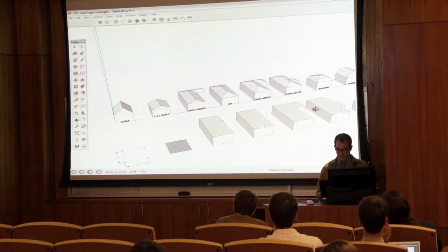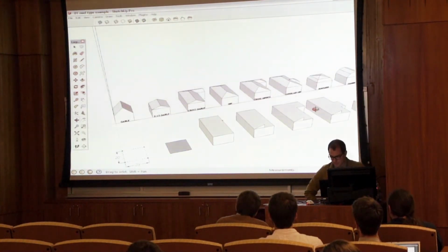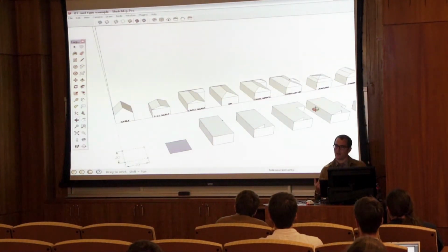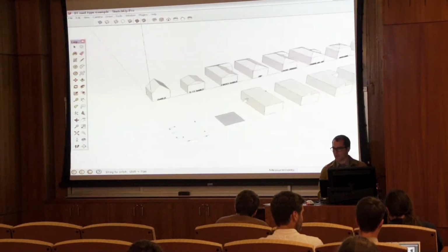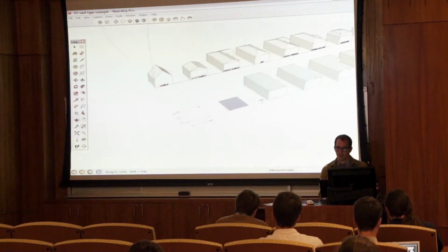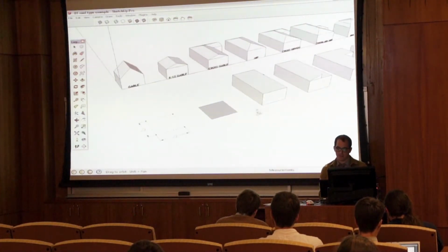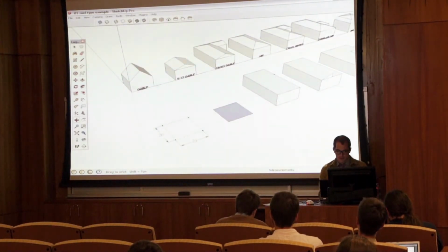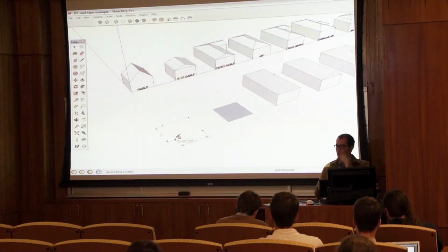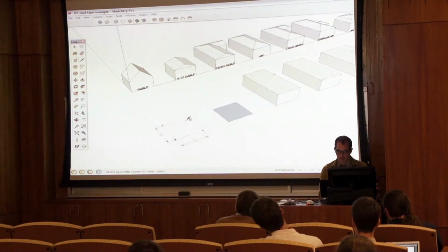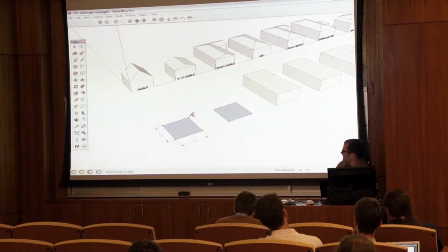For example, in the gable roof, or even the second one, there's 2 or 3 different ways that you can look at modeling this. So I'll ask for some of your input on how you would approach modeling this, and then maybe give you some insight on some faster and simpler ways to do it. So first, to draw this gable roof here, just take the rectangle tool. You'll see I have some dimensions just added down there, as well as some guides. So go ahead and just trace a 20-foot by 20-foot rectangle in your model space here.